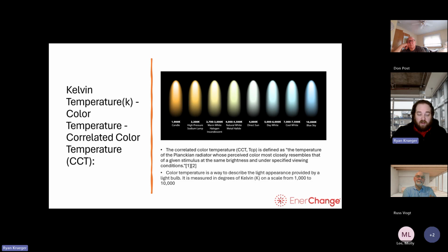Within lighting, fluorescent is going to be offered between 2,700 Kelvin and 6,500 Kelvin. And it's just a game of matching that existing color temperature. In church sanctuaries, you have to get it right. If everything in there is a specific color temperature and you change it all to 5,000 K, you're going to get yelled at, and then you're going to have to redo everything.